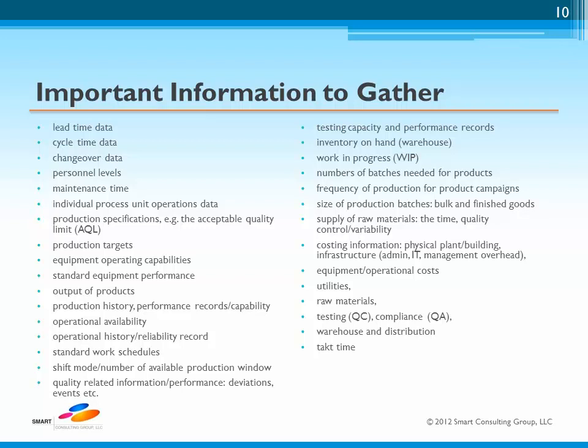The tools. Several tools can be used to create and identify root cause in a value stream map. Some of these include the box score, debate charts, plan, do, check, act charts, Kaizen storyboards, fishbone and 5 whys analysis. As you review the process value stream map and plan your transition to the new future state situation, the project team identifies many sub-projects that will be needed in order to complete and effect a system change.